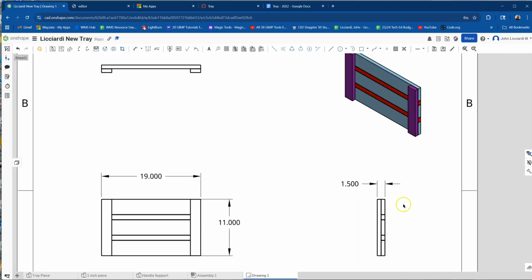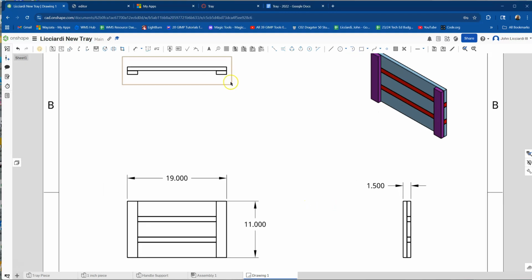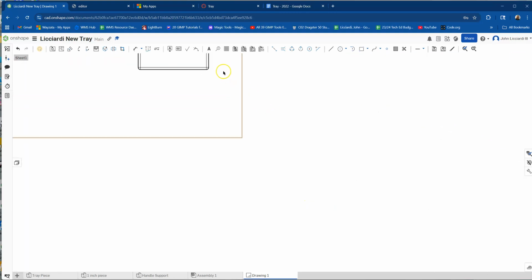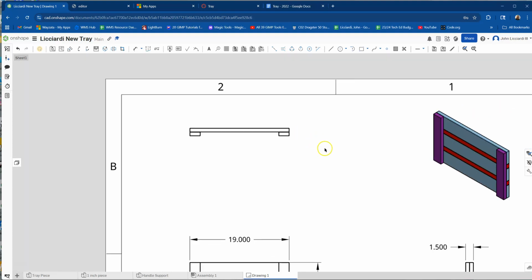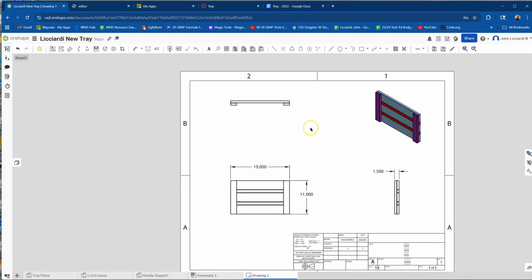That's gone. And then last but not least, normally we would do a radius, but I'm going to do that in the next piece. The radius is that curvature, that fillet that we put on. In the assembly view, we don't need it as much, but for the rest of them, we should be doing that, absolutely. So those are the steps: you insert the front, you project the top, you project the right, you project the isometric, and then you give overall dimensions. In the next video, I'm going to go over all the pieces together.